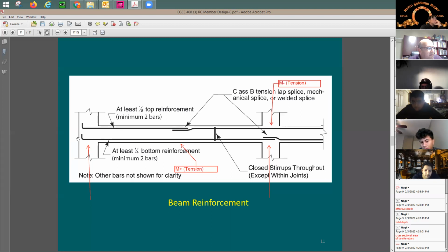These rebars, you cannot bring one piece of rebar and run it across the entire building. You need to start and stop the rebars, just because of how people would handle it, right? You have iron workers, they need to handle the rebar, take it, put it in place. This is going to be very frustrating if you try to take one piece of rebar and install it in place. So in a case like this, you need to start and stop the rebar. So in reality, this rebar doesn't do this. In reality, you're going to have a bar like this.